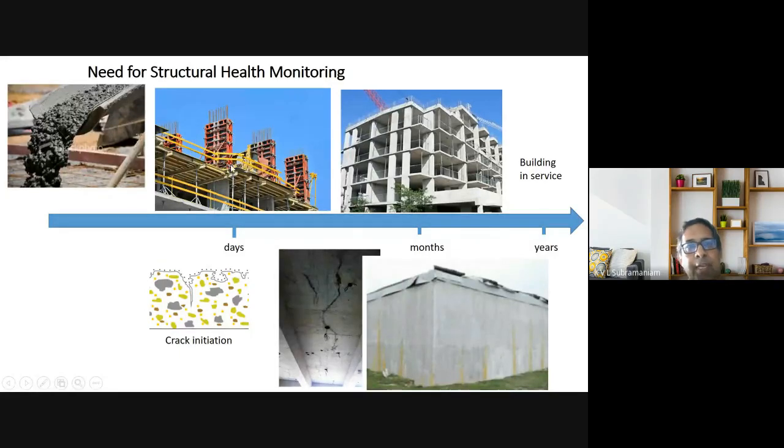So what you see here is a formwork, the shape that you want to give the material. You pour it into that formwork, and then slowly with time, concrete ages. It transforms itself from a fluid state to a solid state, and the solid slowly gains strength. Once concrete is strong enough, we remove the formwork, and then what you see is this concrete structural element. So you see the beams and the columns and the concrete slabs. There's a complete transformation that takes place. It starts out in a fluid state, ends up as a solid, and the solid slowly gains strength over time. So that's the life cycle of the production part of concrete.